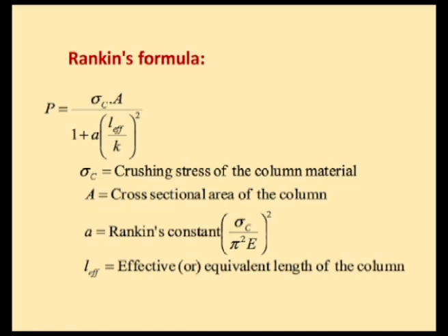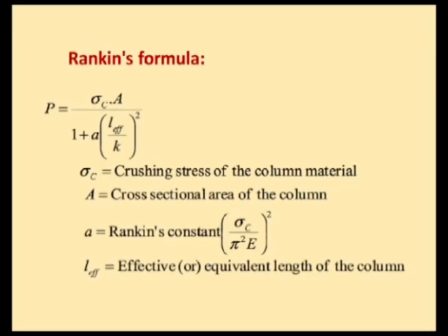And then L effective. The effective length we need to make use of depends on the end conditions of the column. We have already reviewed the different effective length cases. When both ends are hinged, L effective equals L. When one end is fixed and the other end is free, L effective equals 2 times L, and when one end is fixed and the other end is hinged, L effective equals L by root 2. So, with this knowledge, we will now see a problem.